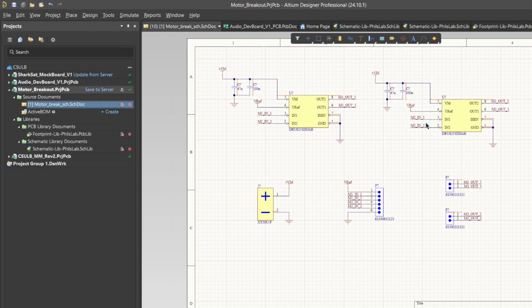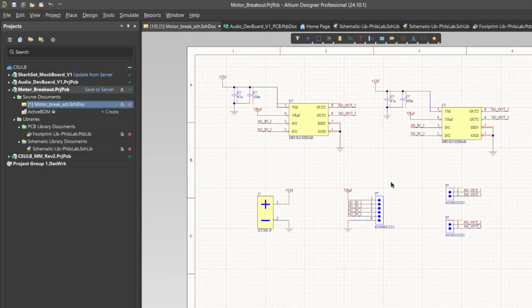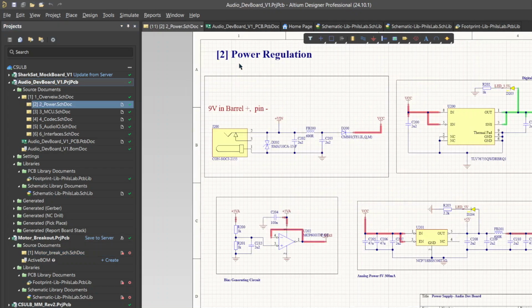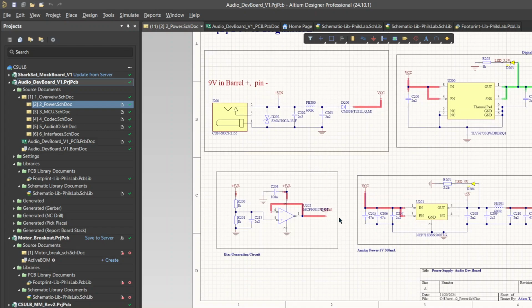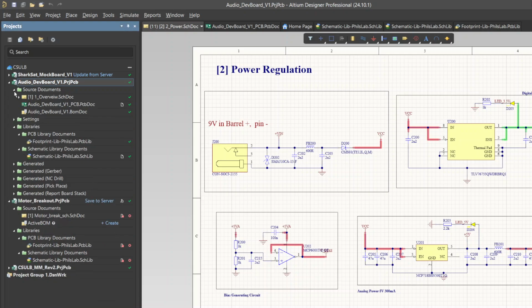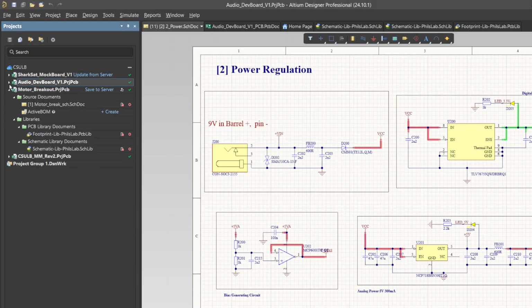However, before I move away from the schematic, there's a couple of nice, tidy things to do that I would like to make our schematic look a little bit cleaner. For example, here are some schematics that I've done in the past, and you'll notice that it's really nice to do a little bit of labeling on things, and boxing off different areas of it. The only reason is it's just nice to look at, and also helps the next person who's looking at your schematic to understand a little bit better what's happening.